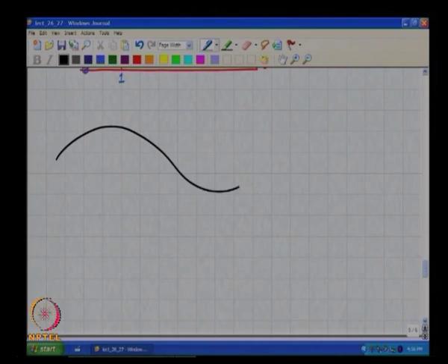The input is some low frequency waveform like this, right, and if the oversampling ratio is very large, this is a grossly exaggerated picture, right, where the oversampling ratio is not very large. Okay, you can see that one cycle is occupying perhaps 10 or 12 units of time. So, if you have a highly oversampled signal, the periodicity of the signal will be many samples.